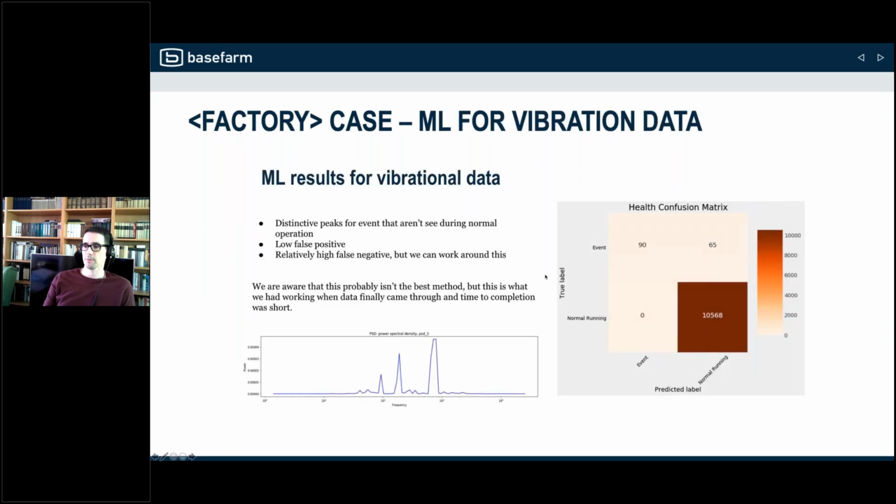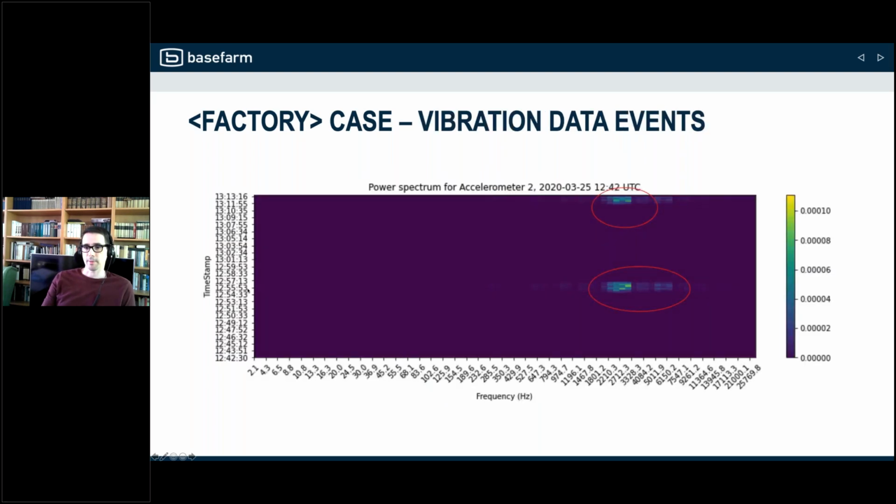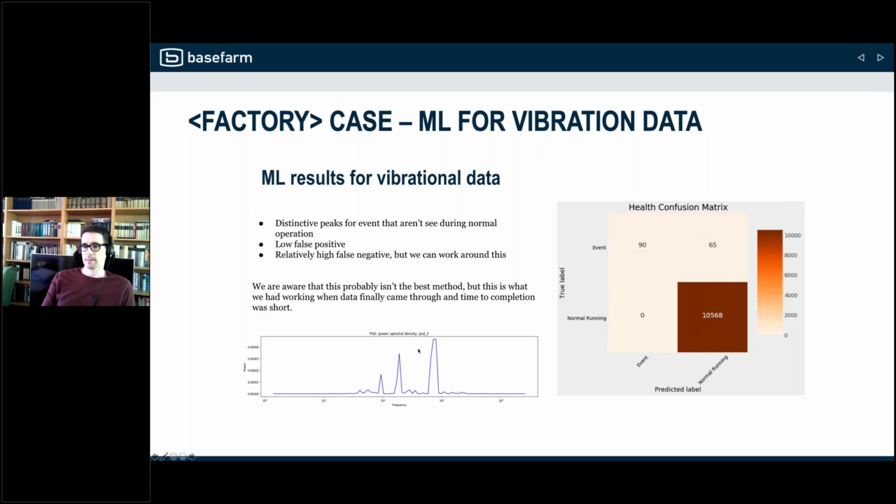And the next picture, what you can see here is basically the spikes on the horizontal line of the previous chart. So if I go back here, let's say if you pick 1255 and you imagine a horizontal line through the whole graph, you can also see that outside the red circles we have some colors. So these are spikes, and these spikes are showing us that there is some problem, some vibration-created issue on the line.